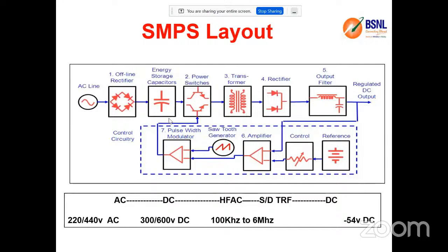The reason for high frequency AC is that we can reduce the size of the transformers and minimize the effort for the regulation part, so that we have a more steady state DC value. That is the reason we switch to high frequency AC. Then stage number 4 converts it back into DC. I cannot expect the Tamil Nadu Electricity Board or any other board to give me a high frequency AC, because it is designed for 50 hertz. But to have an efficient, space effective and well controlled rectifier, we first convert AC to DC and then DC to high frequency AC.